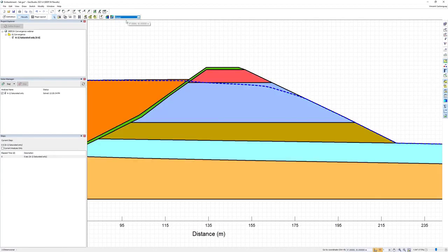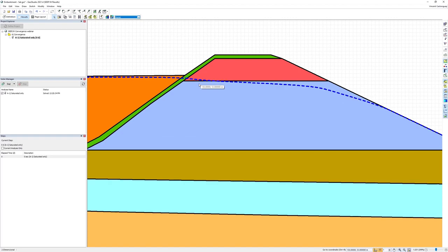Viewing the material colors in conjunction with the position of the piezometric surface allows me to identify the materials where unsaturated flow develops. In this case, the orange, green, red, and blue materials are all crossed by the piezometric line. The material portions that lie above the piezometric line have negative pore water pressure, where unsaturated flow will occur. Based on this two-step approach I laid out a moment ago, these materials should be simulated using a saturated-unsaturated material model.